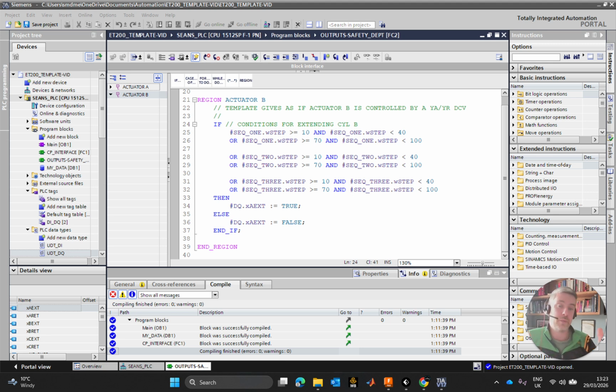For cylinder B, whenever we give a pulse to terminal 12 of the solenoid, it'll let air out of port 2 of the valve, and it'll retract the cylinder. So that is likely to happen in one of our cylinders controlled by a solenoid actuated solenoid return valve. For extending and retracting B, I do not need a greater than or equal to, right? All I need here is just my equals to. There is no ands here.